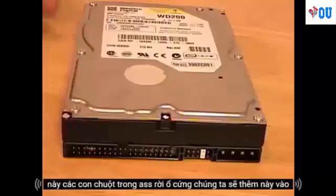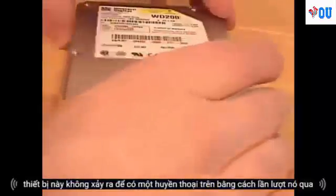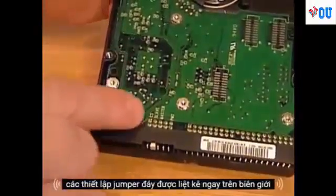This device is going to be our slave hard drive. We're going to add this to the primary controller. This device doesn't happen to have a legend on top, but if I turn it over, the bottom jumper settings are listed right on the board.